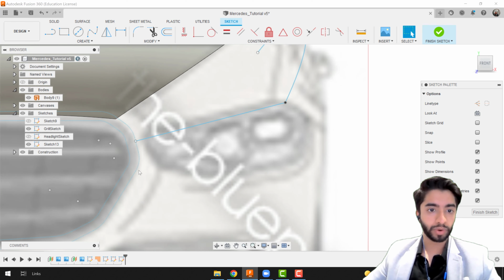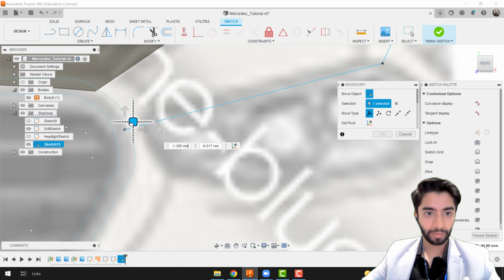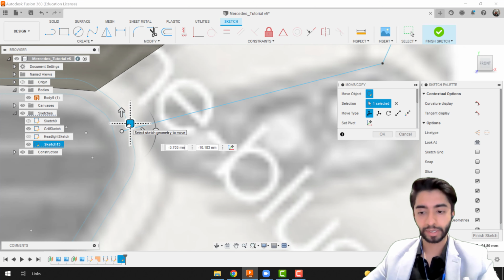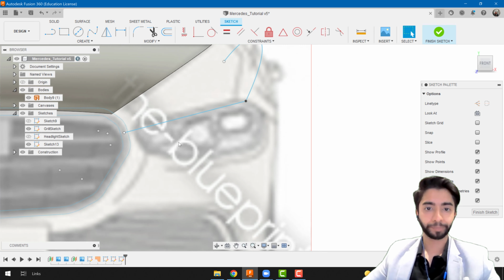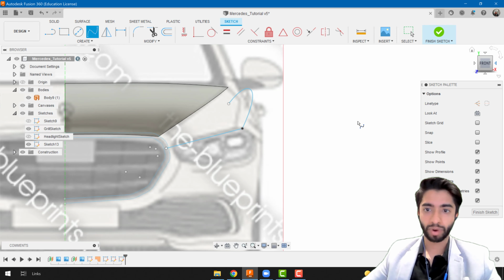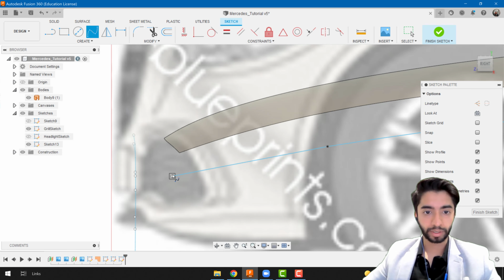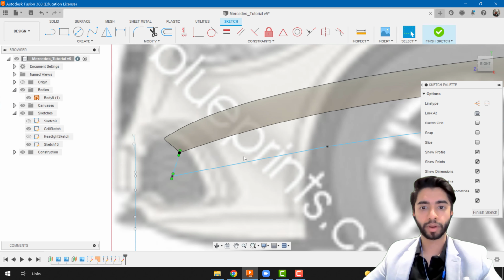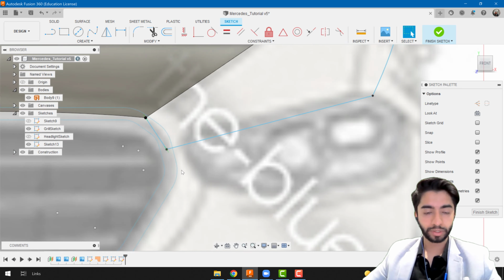Now also put your grill sketch on, and make sure that this point is a little bit more inside than that intersection there, right? So make sure that point is all over there. Again, press Fit Point Spline, go back to your right, orbit a little bit, and now we can go ahead and connect that point to that point there. Okay? So that looks good.